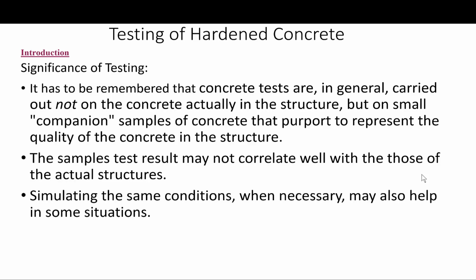This discrepancy arises from differences in the many variables that determine the behavior we just mentioned. Although standard tests may well give some indication of concrete quality, many problems have arisen where concrete samples gave acceptable test results while the concrete in the structure was of lower quality and behaved quite differently.